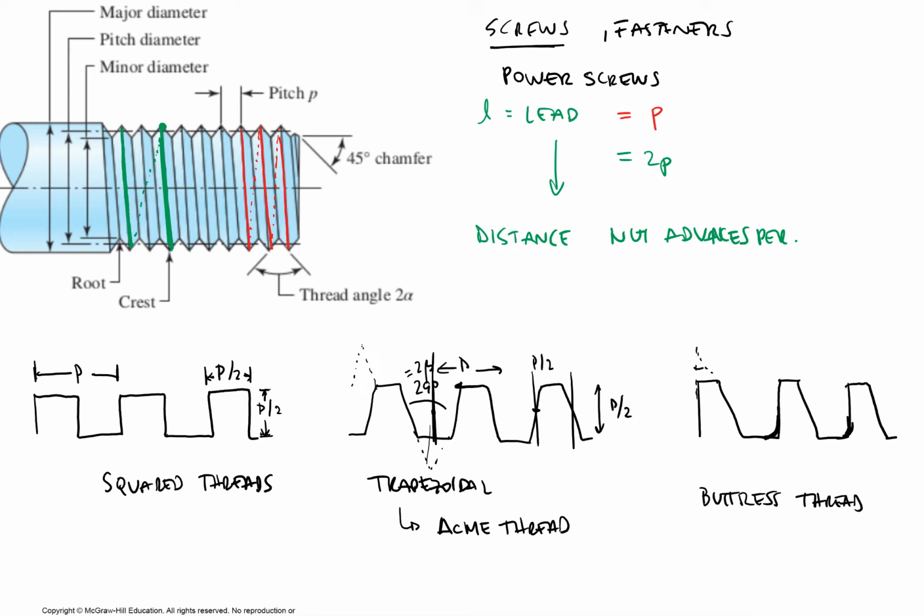But the difference between those two, mainly, there are other differences, is that power screws are used to transfer large amounts of power with not a lot of cycles or repetitions, or fast speeds. Gears are usually used for the opposite, again, not always: not a lot of power transfer, but a lot of cycles and a lot of RPMs.